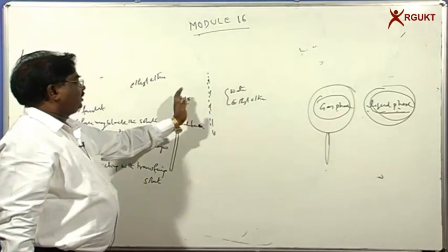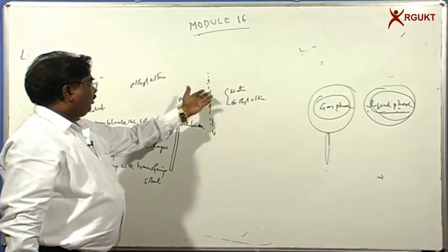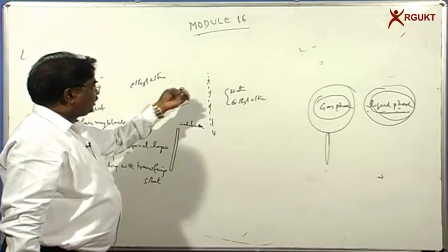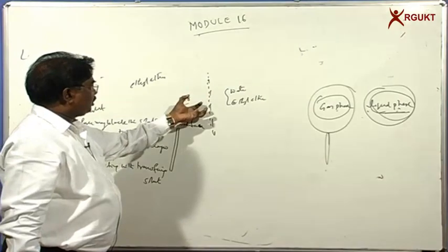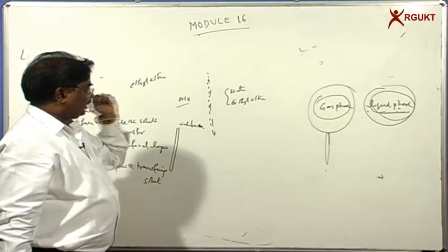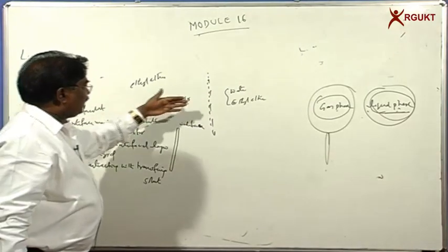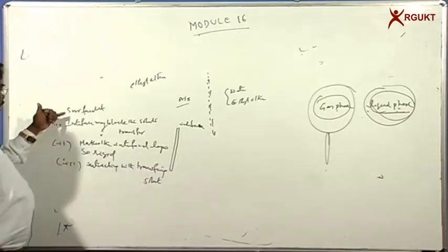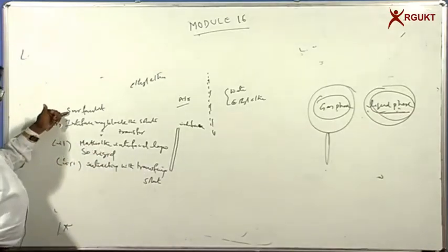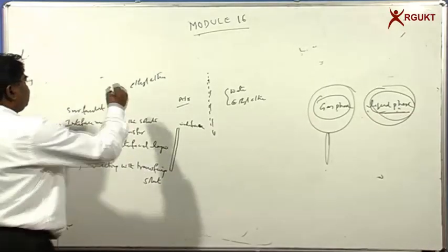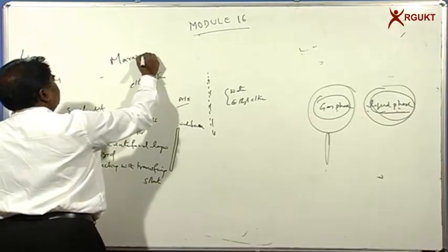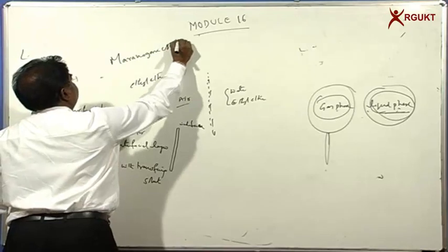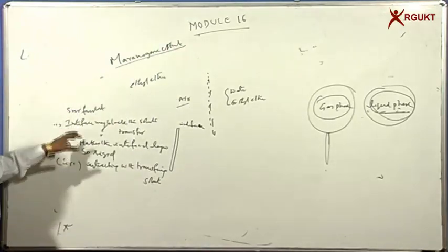water phase to the air phase, when the ethyl ether reaches the interface, it creates so much turbulence at the interface. Because of this, the overall mass transfer coefficient at the interface is going to increase, and because of that, the mass flux is going to increase. But when you talk about certain types of particles, this is called the Marangoni effect. And in some cases, what will happen?